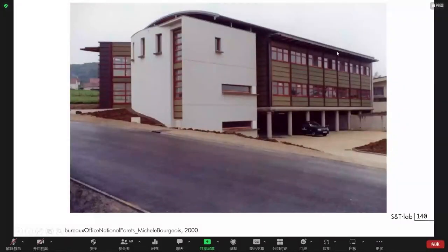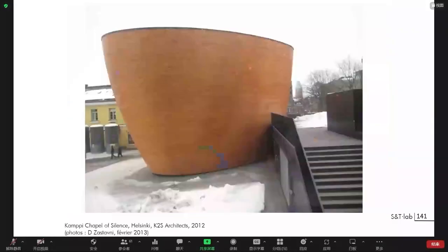Again, here this part of the building is protected from the ground with a parking zone made of concrete and an overhanging roof system. But what is interesting in this building is that you have a protective layer in red and green that is not quality wood, but can be replaced over a long time. And when you are too much exposed, you can just use another material to protect it in some places. And that could be a real strategy that will be defining your architecture.